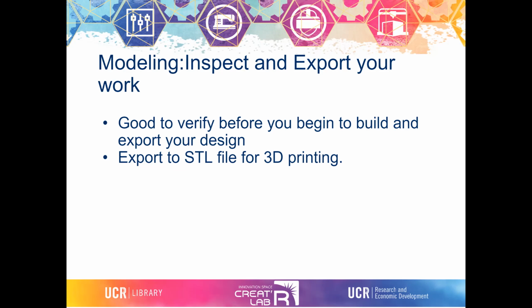That way, you know that right before you're gonna start to model, everything's good. So I recently created a case for my iPhone. I used the website that I showed you. I downloaded a model of my iPhone. It was the 13, I think. I did a quick measurement on Fusion and in the real world, and everything matched up. So I knew right then and there that I can continue and start modeling my case so that when I printed, it would work. I printed it with TPU, and it fit perfectly on my phone. All the holes matched the buttons on my phone, and I was able to use it.